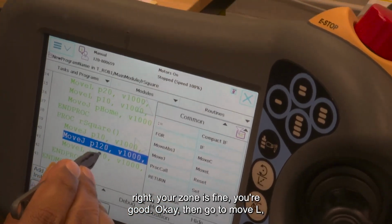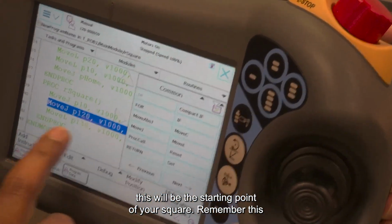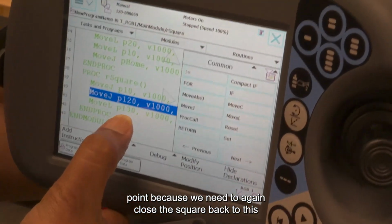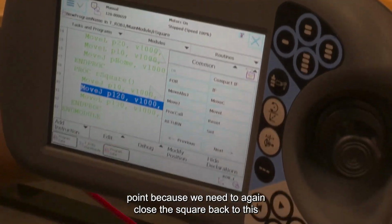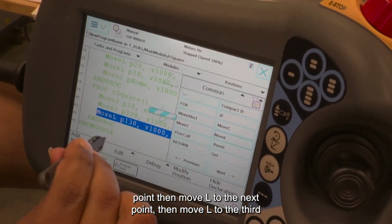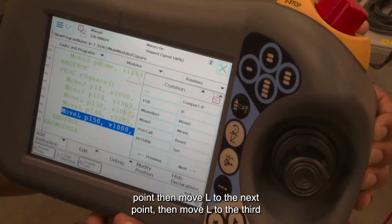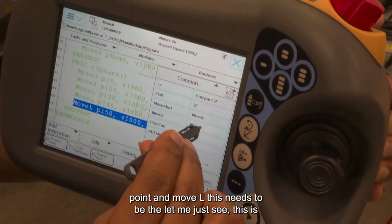Okay, then go to move L. This will be the starting point of your square. Remember this point because we need to again close the square back to this point. Then move L to the next point, then move L to the third point and move L.